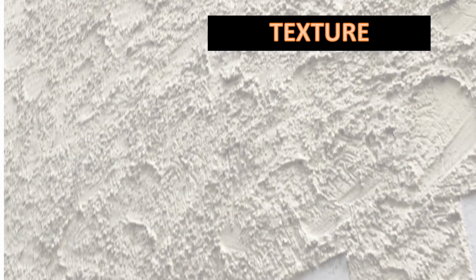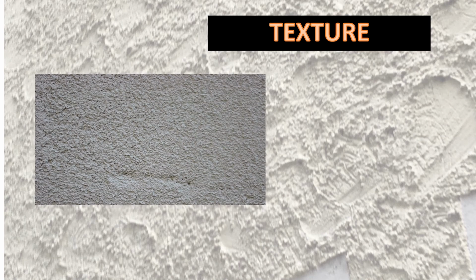Both materials have sand, but cement finish coats have more body due to the cement and lime binders. This means cements also have greater texture capabilities. They also can hide imperfections in the base coat better than acrylics.